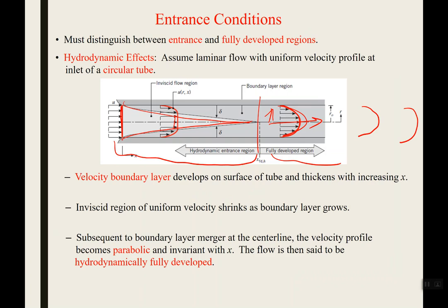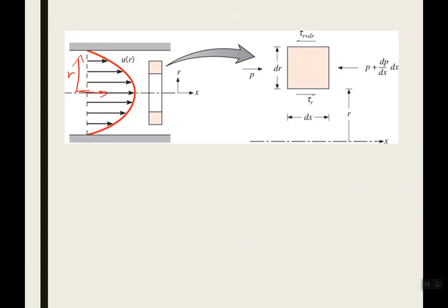If you remember, we still have boundary layers that form as the fluid enters the pipe, but eventually those boundary layers will converge into each other and you'll get what's called fully developed flow. So once you get fully developed flow, basically your heat transfer coefficients will level off and they'll just be constant from the point of starting with the fully developed region all the way to the end of your channel. So we might have to deal with things like local heat transfer coefficients at the beginning of the pipe, or if the pipe is quite long, then we can neglect what's happening at the entry region and just treat our heat transfer coefficient as being constant throughout the length of the pipe. So we'd basically be neglecting that entry region.